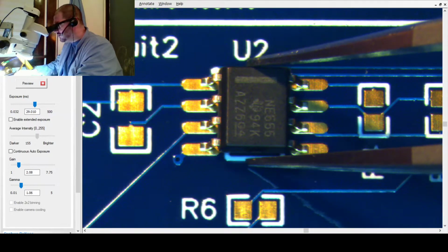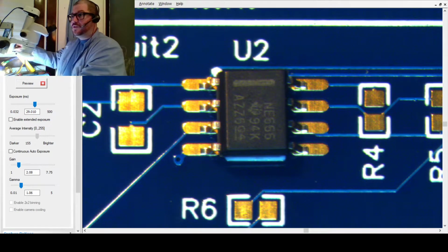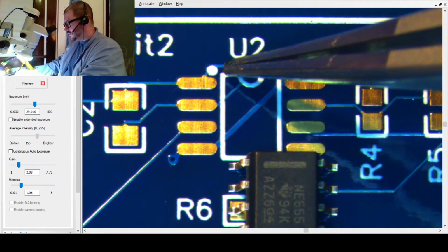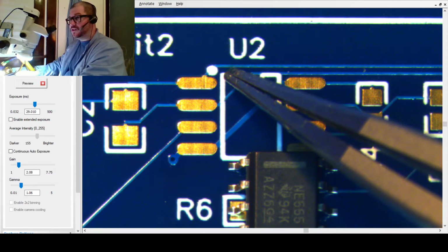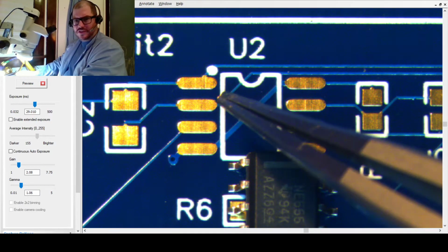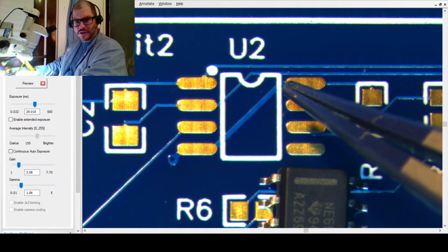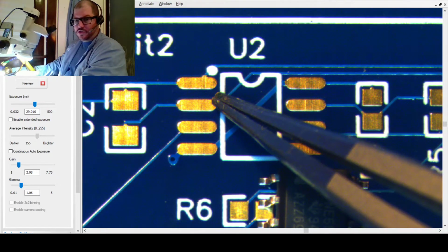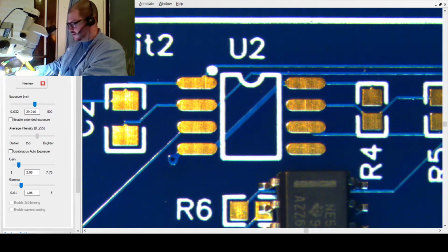Anyway, if you were to notice, this chip actually fits on these pads very, very nicely. It's almost like it was made to do so. And if one were to take a closer look at the silk screen layer, there is a dot indicator up here, this indicates pin 1. Most chips that I've encountered that have pins on the outside that you can see go starting from one pin and then counterclockwise, or for you British folks out there, anti-clockwise, whichever. Going counterclockwise around it, it goes 1, 2, 3, 4, 5, 6, 7, and 8, and then goes around in a circle like that.